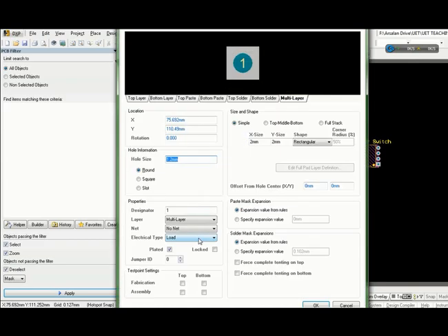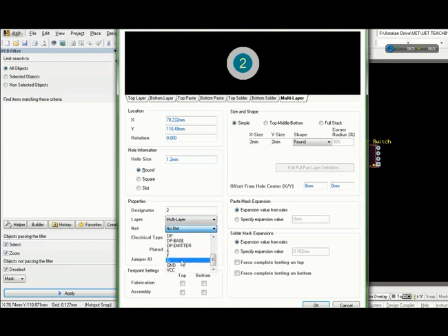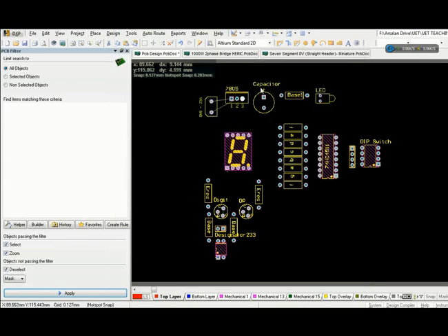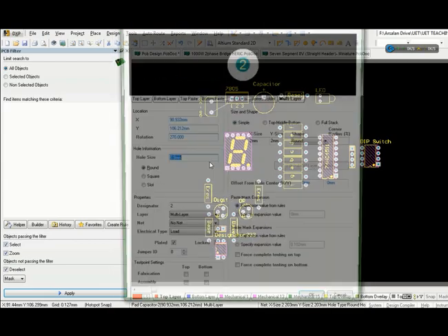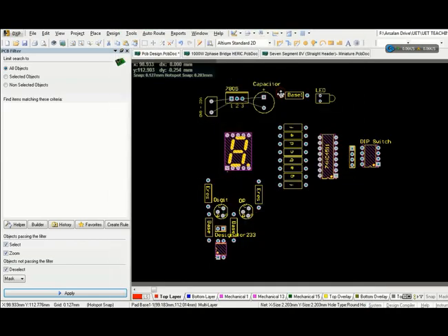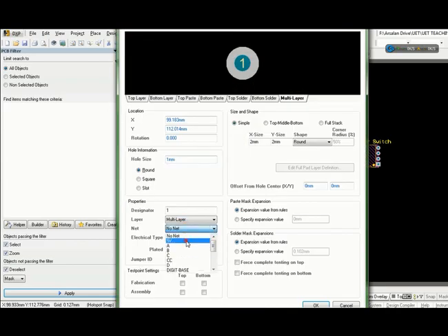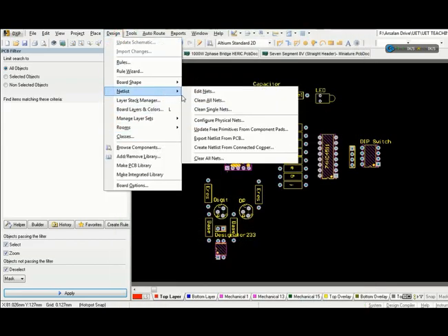You can see now I am pointing the nets on the PCB diagram, and I am using the nets over there for all this. So you can see the TO220 packaging. This is the new thing for you, and I have shown you the transistor also physically today, and I have shown you how you are going to hold it. The footprint of the transistor also has the logic over there, the 1, 2, 3 pins.